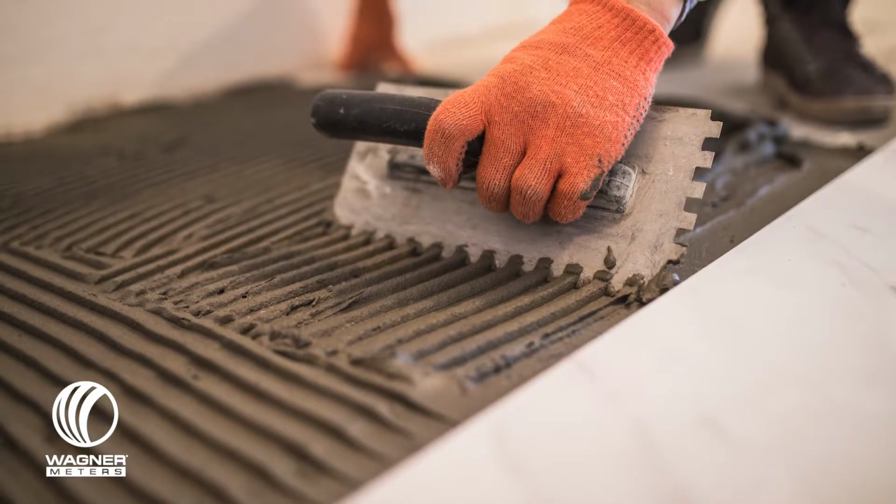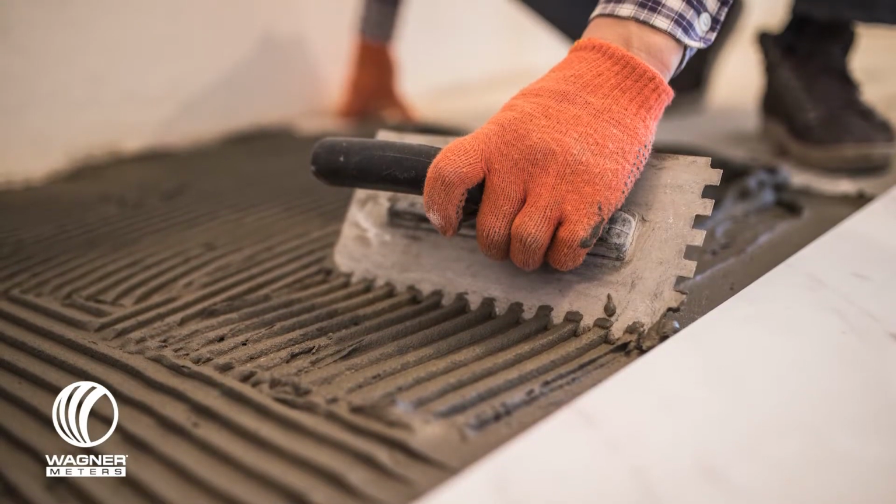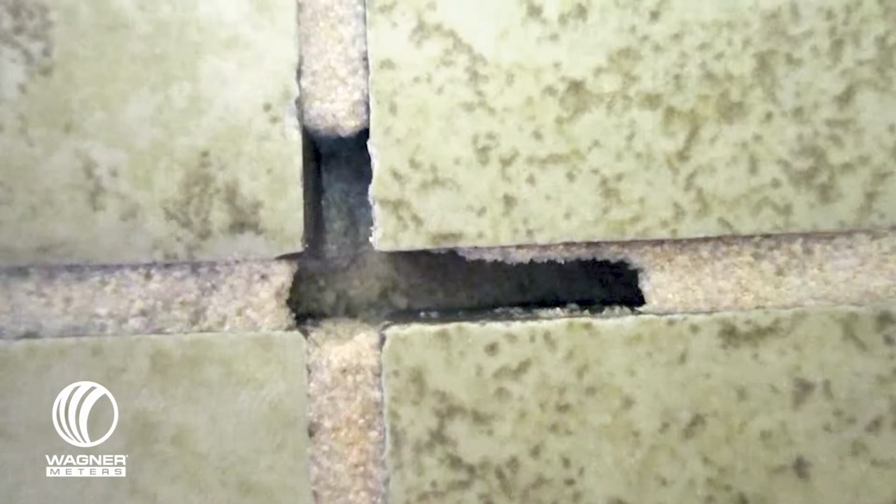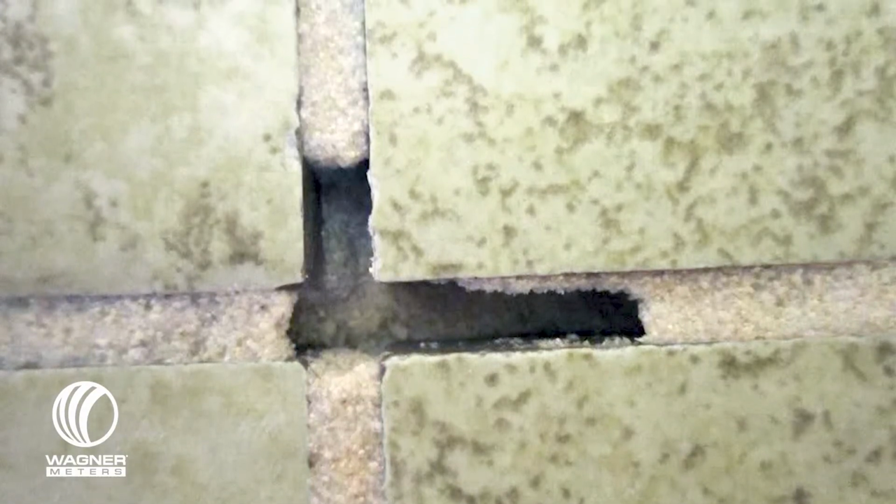Number three, grout or cementitious bonds. Damage to grout or cementitious bonds happens if the slab was not dried to the required specs before installation. This means the natural moisture migration of the drying concrete will impact the grout. In extreme cases, excess moisture can lead to flaking or chipping of the grout, which, of course, would need replacing. Sometimes this can be minor cosmetic issues, but why take the risk?